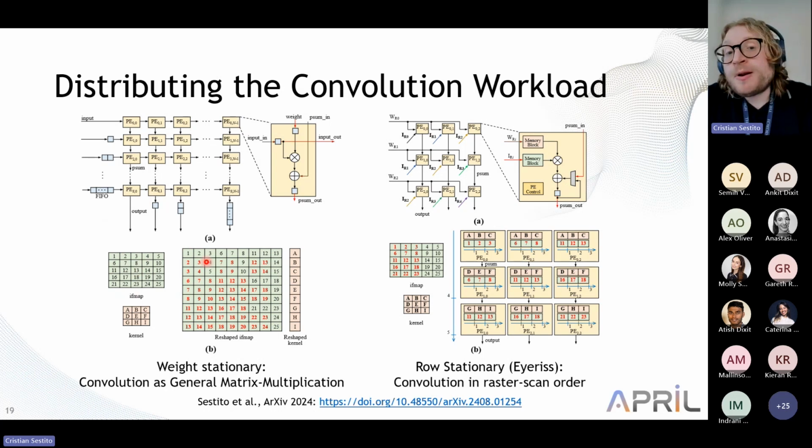What is the problem of this approach? We have a lot of redundancy. Basically, we need bigger memories to save data and to repeat the same piece of data multiple times. To be specific, the repetition in this image is highlighted by the red numbers, and as you can see, we have a considerable number of repetitions. So definitely, this is degrading in terms of memory access, because we will need to access more frequently, basically fetching the same piece of data multiple times.